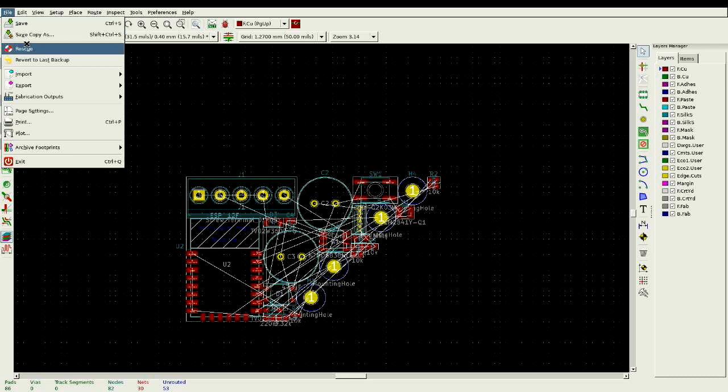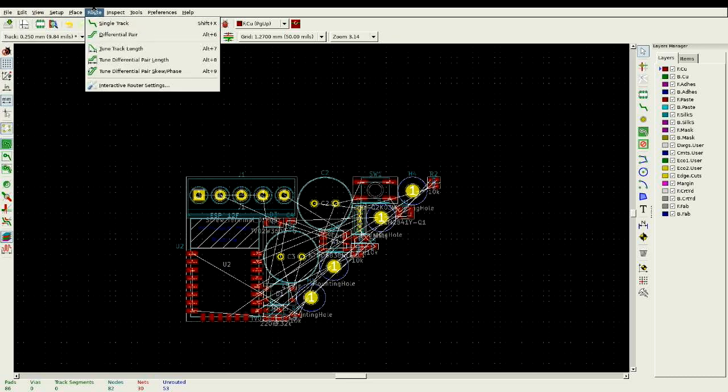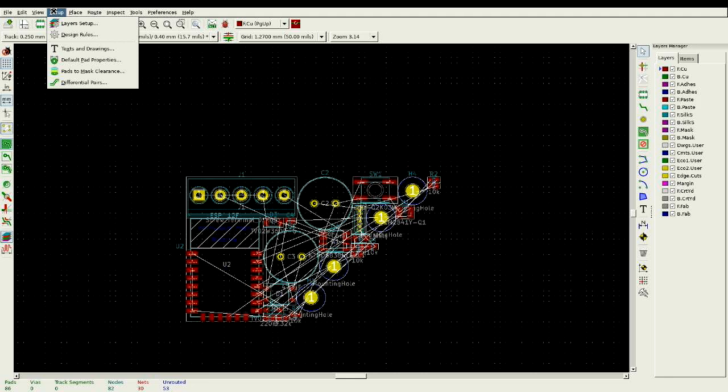Before we keep going, on your piece of paper, where's mine? On the piece of paper on the PCB side, there's two dialog boxes. Unfortunately, between 5.0 and 5.1, they've changed these dialog boxes a little bit. I'm going to be showing you on the screen the slightly older version. The newer version has the same things, but it's under File, and I think it's File and then Board Setup is the dialog.